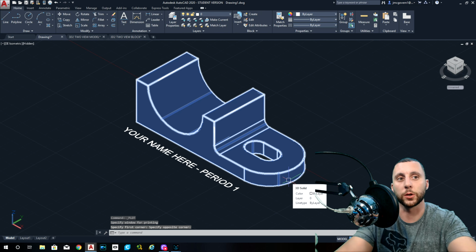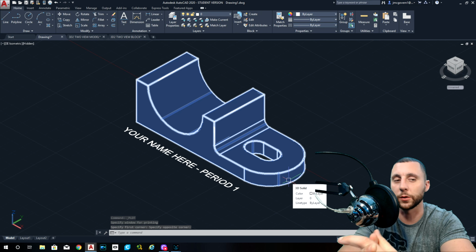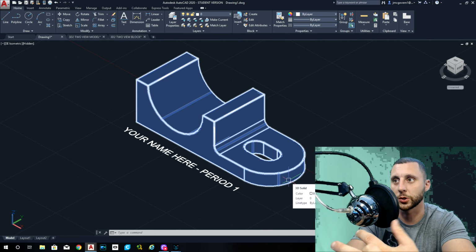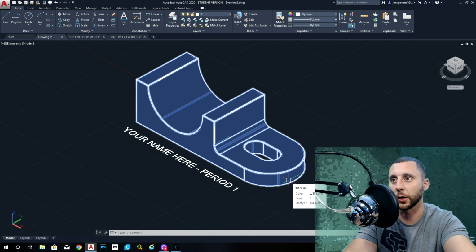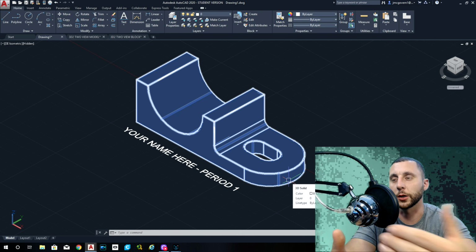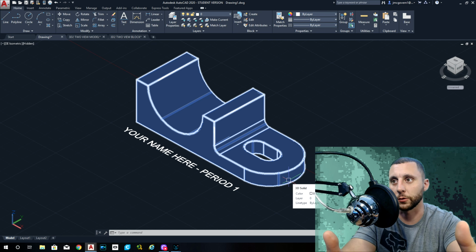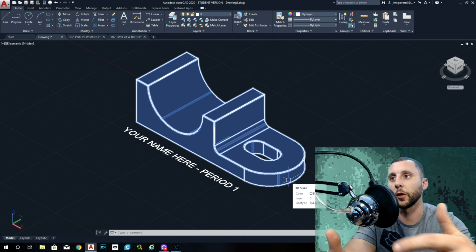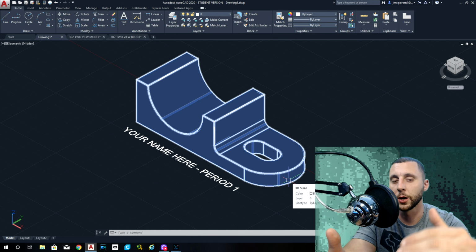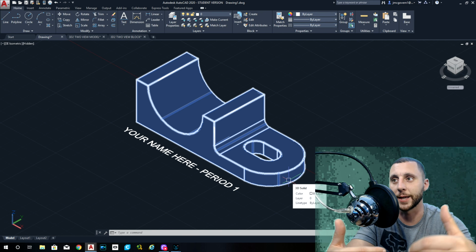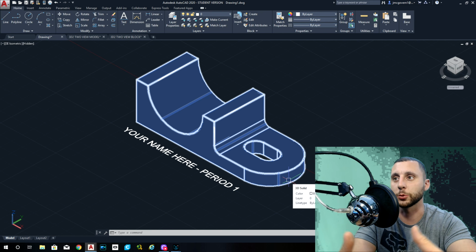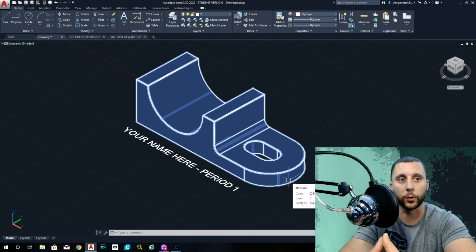All right. So you can see we're already getting a little bit more advanced with our 3D models, because the first one was just a profile and extruded, and it was done. This one was a profile, extruded, then we did a fillet edge to round the corners. Then we actually drew another profile on top of one of those ledges. We joined them together, we extruded it down into the other model, and then we subtracted it away. All right, so it gets a little bit more complicated as we go on.